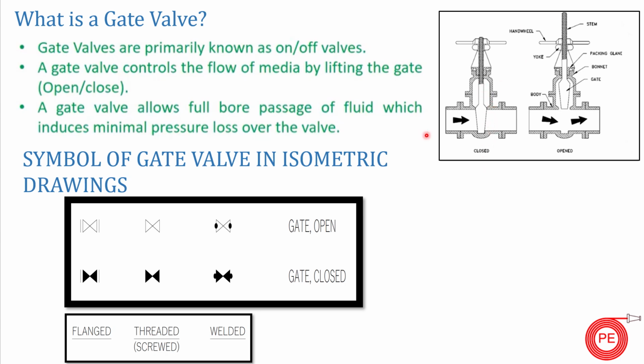So friends, as I already mentioned, unlike control valves or throttling valves, gate valves are not designed to regulate the flow. Keep that in mind, this is one of the confusions people generally have. Gate valves are used widely in water supply networks, industrial pipelines, and utilities, where certain sections must be isolated during maintenance, repair works, or service expansions.